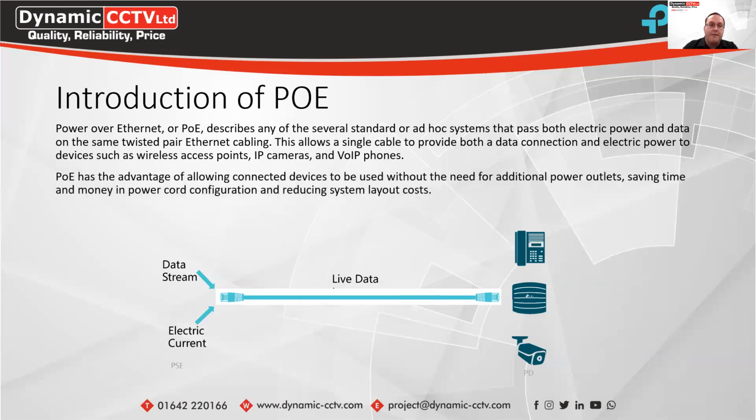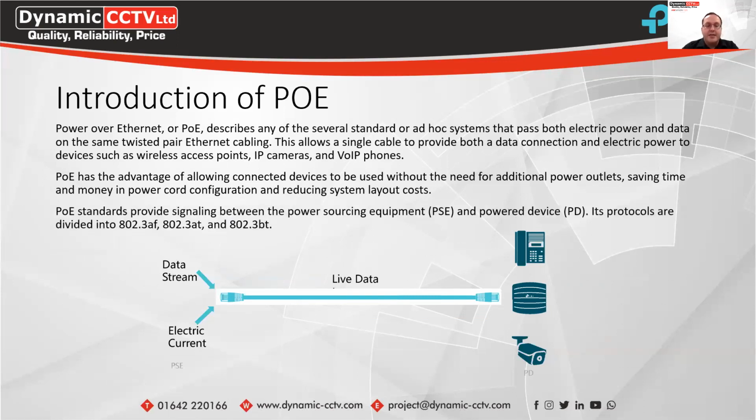And there is a lot of different advantages. Instead of needing to have a local power supply, which you did need to for older analog systems and the likes, with PoE, both the data and power is transmitted over your Cat5 cable between your switch and your endpoint device. There's many different standards when it comes to PoE, and one of the newest ones now is 802.3bt, which is a higher power demand, up to 90 watts in some cases, for the newer higher end range of the PTZs that are available from Hikvision, which do utilize that protocol.